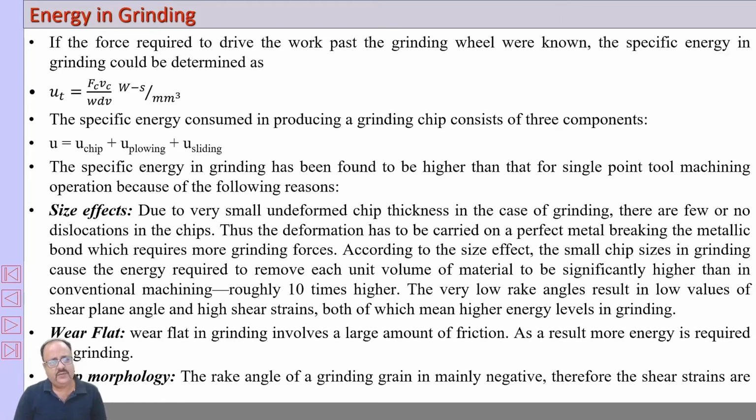So what is the size effect? See, in grinding we remove the material in minute quantities. The thickness is very small. Now in this small thickness, the probability of deformation or dislocations of the material is very low. So therefore, the deformation has to be carried out by breaking the actual metallic bonds, and therefore the grinding force required is much higher, around 10 times higher actually. So that is the size effect.